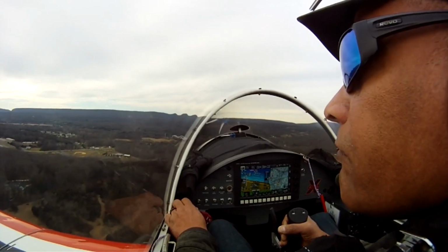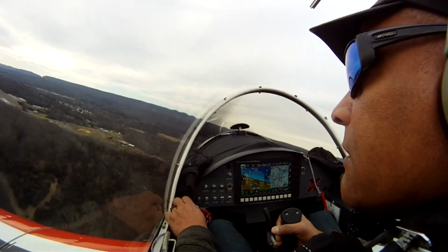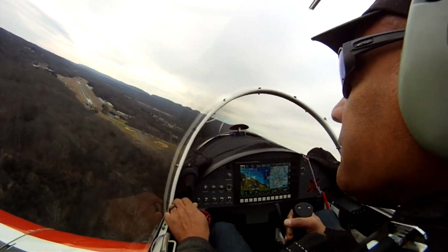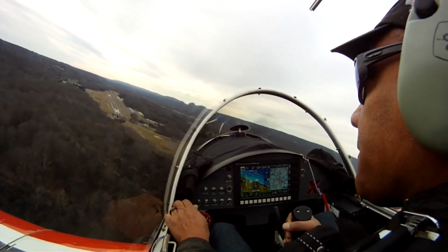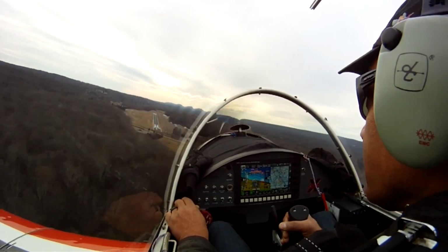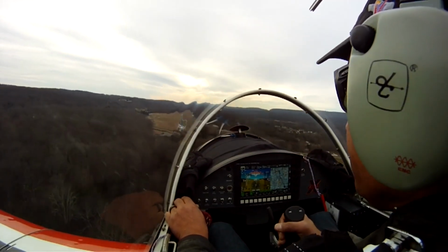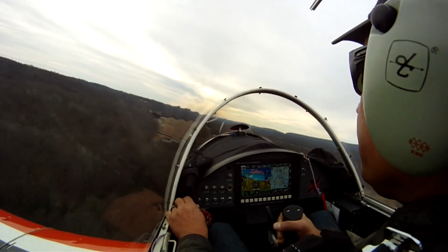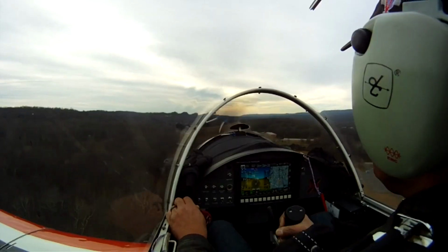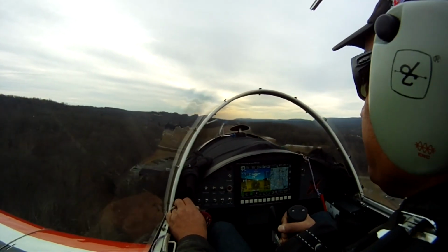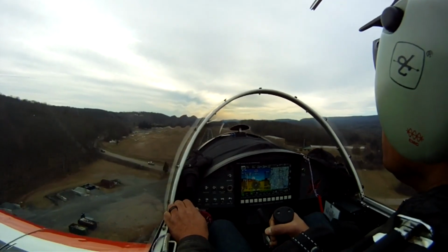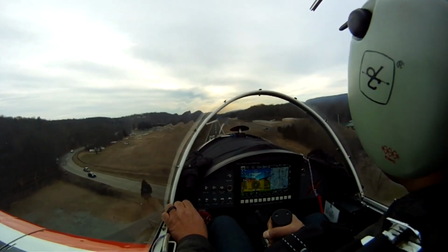As the pilot, you're responsible for designing your landing distance test plan. The Flight Data Viewer only performs calculations based on the data recorded by your EFIS. As you plan, keep in mind that landing distance is affected by flap setting, RPM, density altitude, primarily determined by outside air temperature, wind, aircraft weight, runway surface type, and type of landing, 3-point or wheel landings.